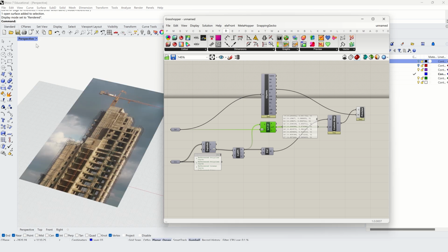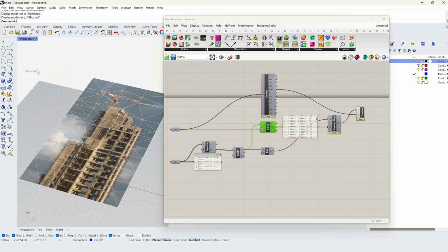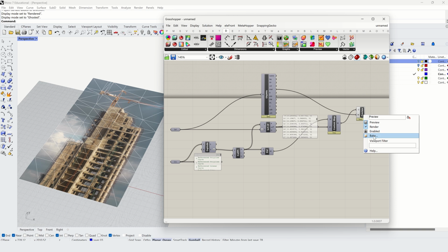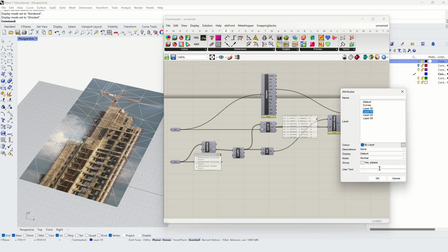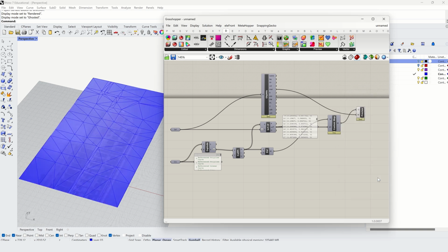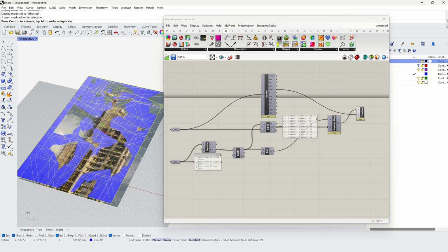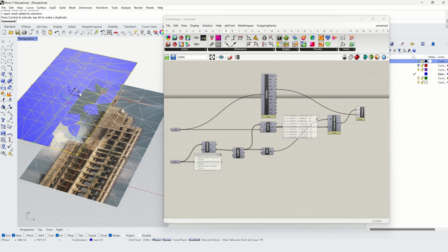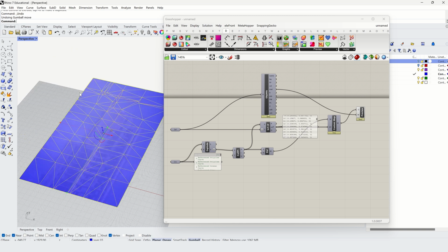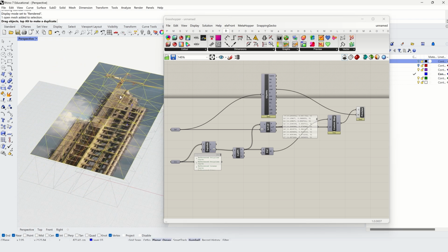Exporting geometry produced in Grasshopper back to Rhino is called baking the geometry. Normally, this can be done by simply right-clicking on the Output Geometry node, selecting Bake, and assigning the layer it should bake onto. Note that this completely severs any connection with the Grasshopper definition. If you change something in that definition, it will not be reflected in the baked object. You will have to rebake. Nor will editing the baked object reflect back into the Grasshopper definition unless it is re-referenced in a new param.